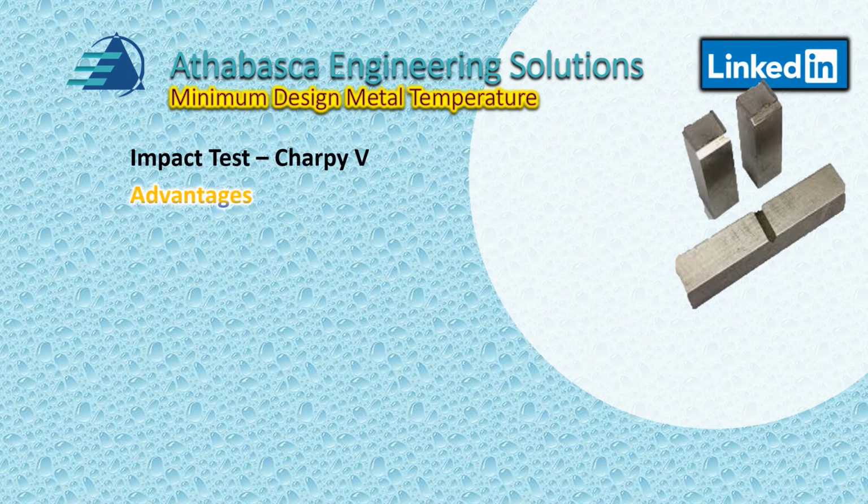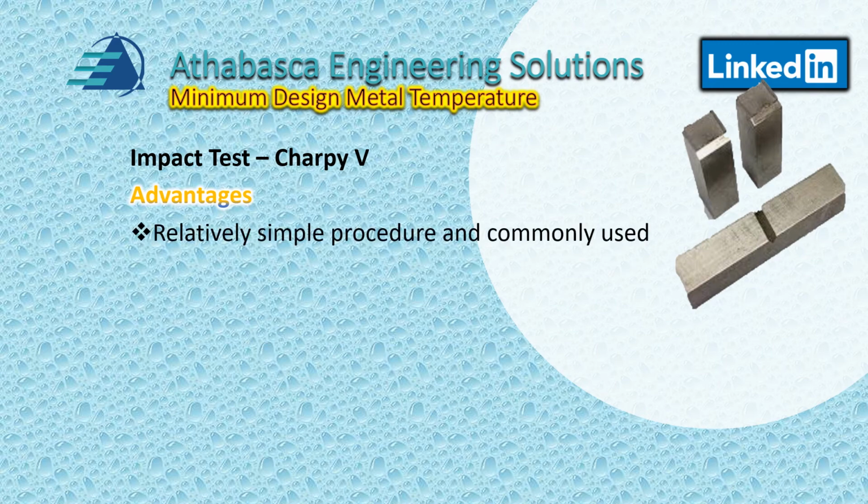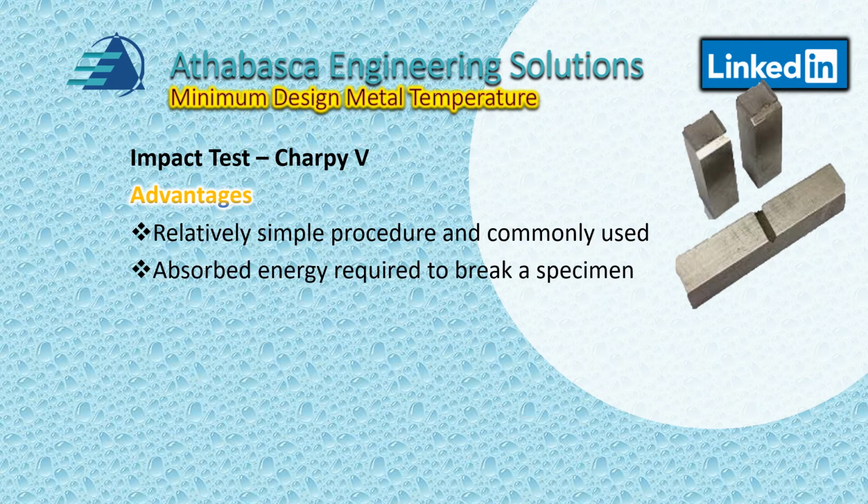Now let's look a little bit more at the advantages and disadvantages of Charpy impact tests. Charpy impact tests are a relatively simple procedure. They're one of the most common methods around for impact testing, so lots of labs are available. It's very well understood. Basically the energy absorbed is the energy required to break the specimen, so it gives you an idea of the percentage of shear fracture of the material.